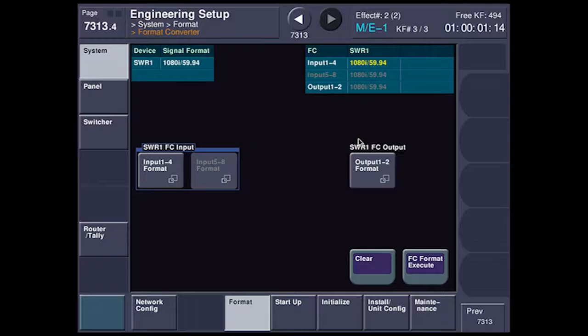Now, frame delay mode can be anywhere from 1 to 8 frames of delay. At 1 frame delay, it's a frame sync. I can put non-synchronous sources into the switcher. From 1 to 8, though, I can dial up and use maybe something like a virtual set system, which might have a few frames of delay, and I want to make the input converter follow that much delay. We're going to set this back to 480i, leave it where it was.